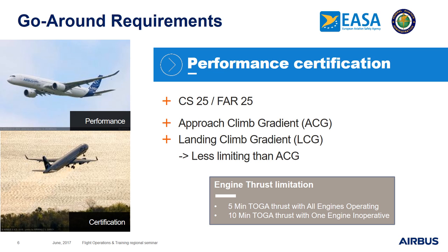In addition to this, the engine thrust time limitation that we know in takeoff is also applicable in case of go-around. So we have 5-minute TOGA thrust with all engines operating and 10-minute TOGA thrust with one engine inoperative.